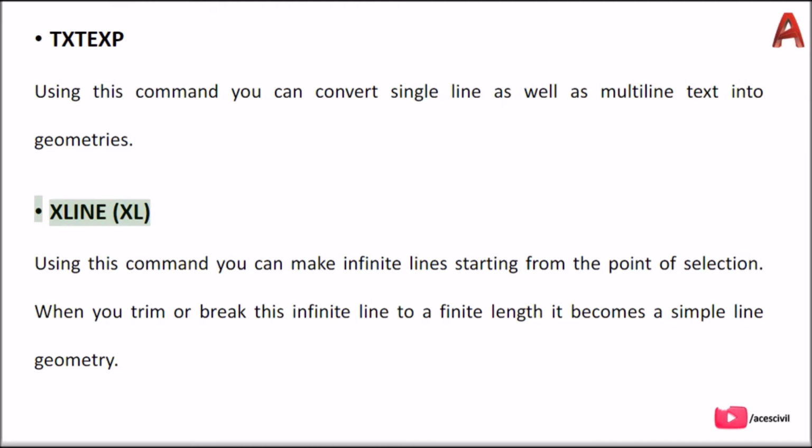XLINE. Using this command you can make infinite lines starting from the point of selection. When you trim or break this infinite line to a finite length, it becomes a simple line geometry.